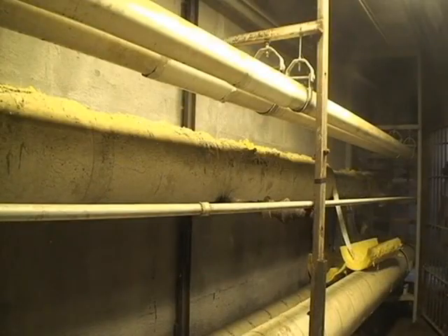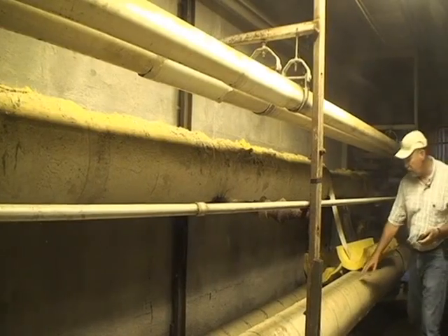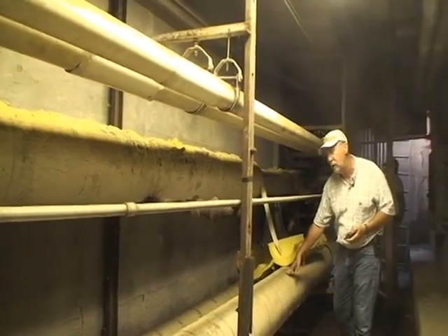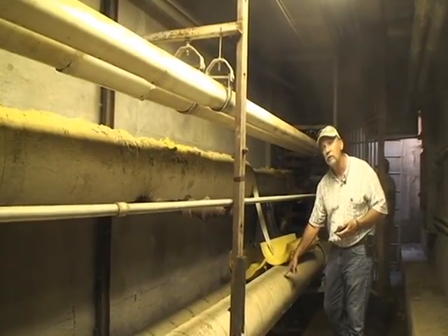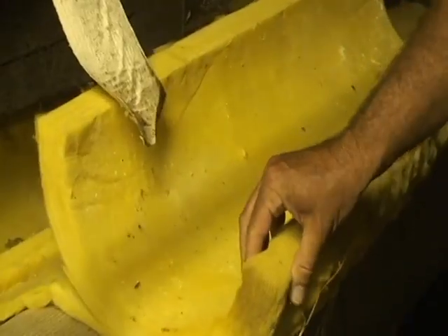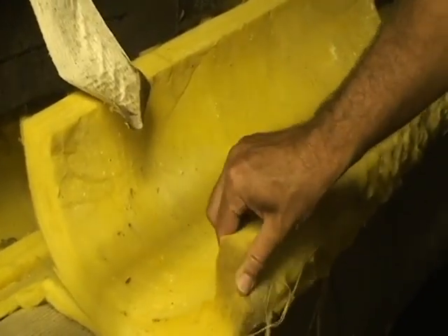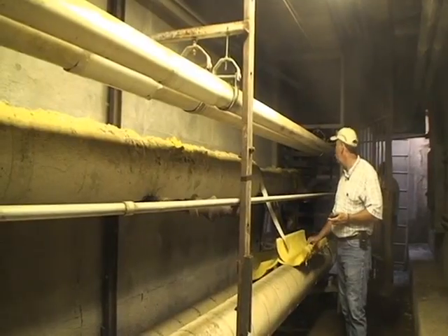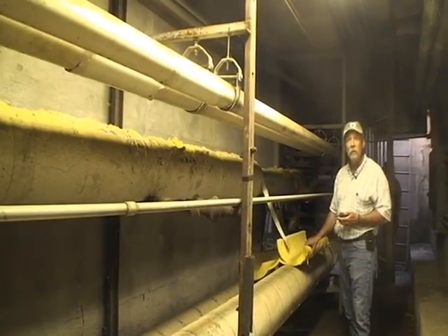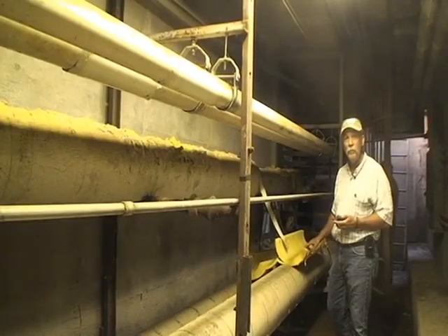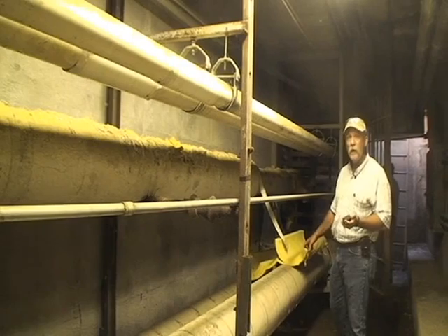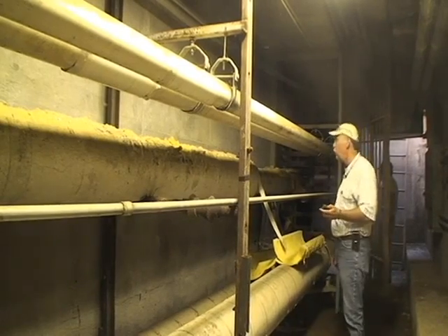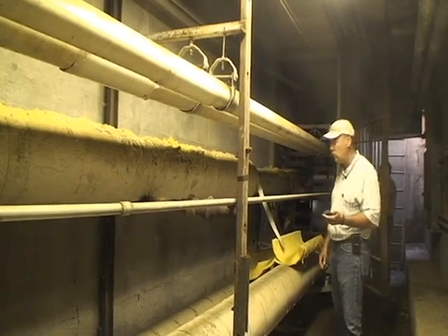If you're looking at insulated steam lines or water lines, occasionally you'll find them covered with an aluminum or a metal jacket of some kind, and they're banded on. You need to look underneath that jacket at some point to see what kind of insulation you'll find. This particular piping has yellow fiberglass batting underneath it. Just because you find fiberglass, you do not know if that fiberglass is by chance covering up the original old asbestos-containing insulation, so you need to either make a core sample all the way down to the pipe, or else you need to find a damaged or exposed piece on the pipe and make a visual inspection on your own.